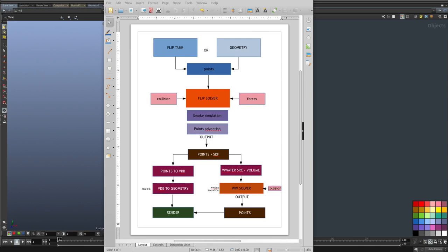And this is what has been used inside the smoke solver. This data is going to be useful for us in various different ways, and we will understand the usage for this data later on. Now we import the points from the flip fluids solver. We need to convert those points into a geometry.